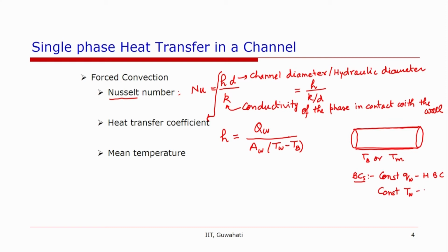So, in this case it is called the third boundary condition, or mixed boundary condition, where one will have a relationship Q wall is equal to h times (T wall minus T infinity). And so, in this case if h is known, then this can be used as a mixed boundary condition. One can see that Q wall from Fourier's law of heat transfer is equal to